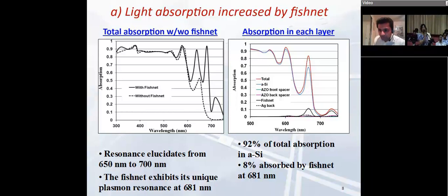Regarding the pattern directly in contact with the active layer, you mean the absorber layer? Yes, it affects. Everything has its effect, and all the different layers have an effect overall, so you cannot ignore that when choosing. Sometimes when you do device modeling, you just consider the PIN layers and the surface layer. But when you do electromagnetic modeling, you don't follow the Beer-Lambert law, which says that absorption increases exponentially. In the electromagnetic simulation, light passes through all the different layers, and each layer has its thickness, which should be optimized.